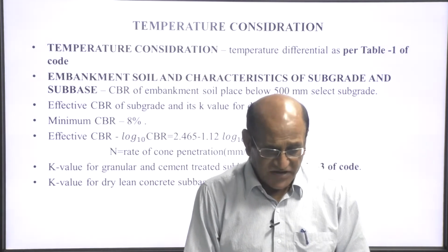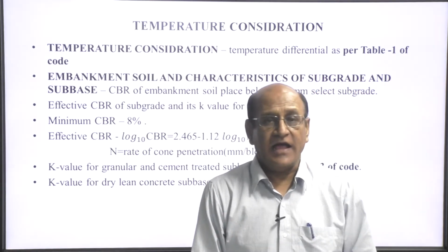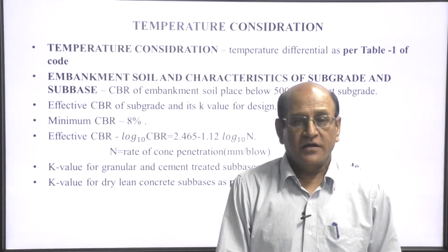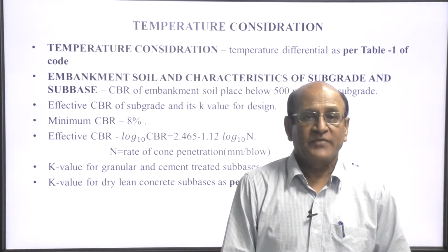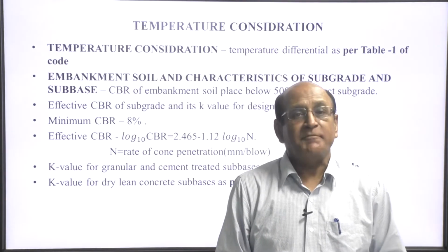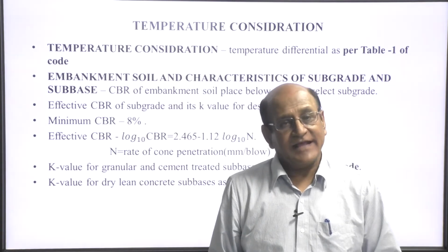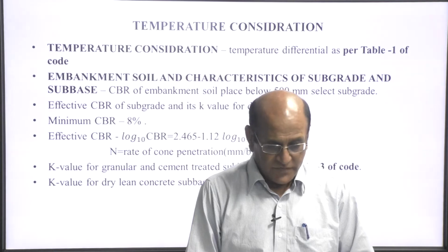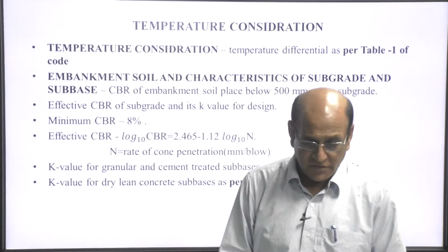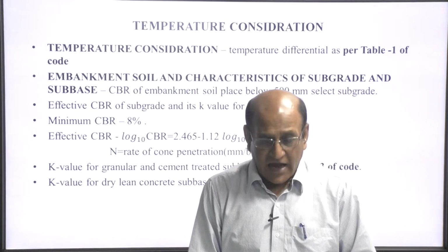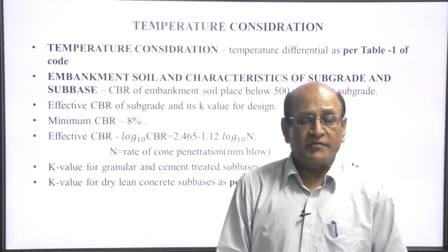Now, come to the temperature consideration. IRC 58 has prepared a chart, and they have divided the whole country into different parts, and they have given the average temperature in different segments of the country. So, for design purposes we have to just choose the temperature differential as per Table 1 of the IRC code 58 2015.